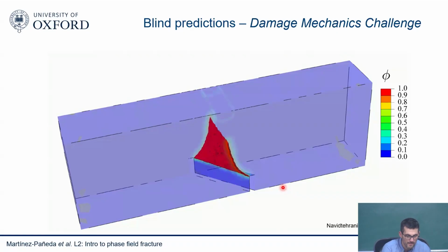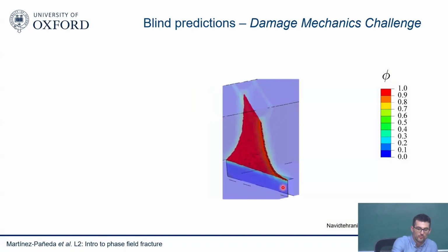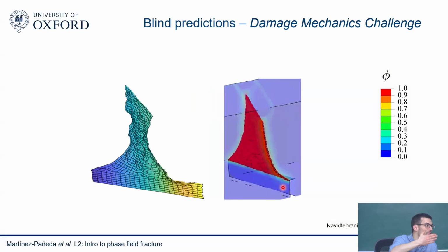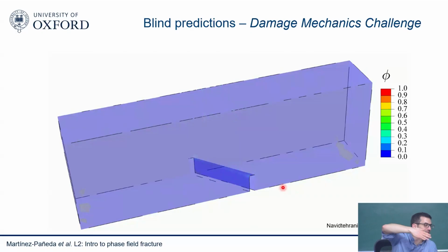Can we say initially it started as a mixed mode crack, now it became a pure mode 1 crack? Yeah, cracks always like to go to mode 1 at the end of the day. So this is what we predicted, and initially it starts mixed mode because of the inclination of the crack. It's tilted, but then eventually becomes mode 1. You don't have to perform an experimental proof for this?